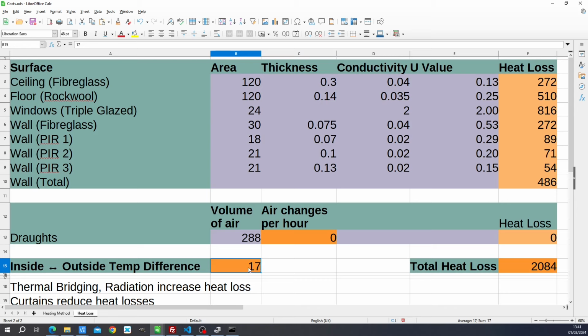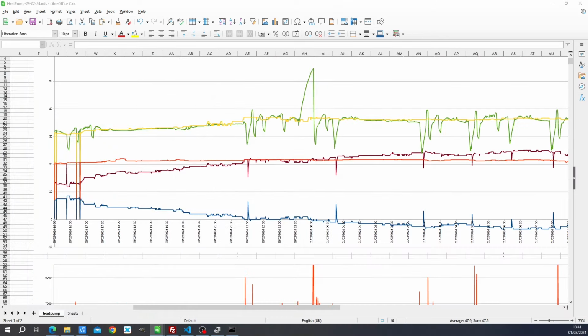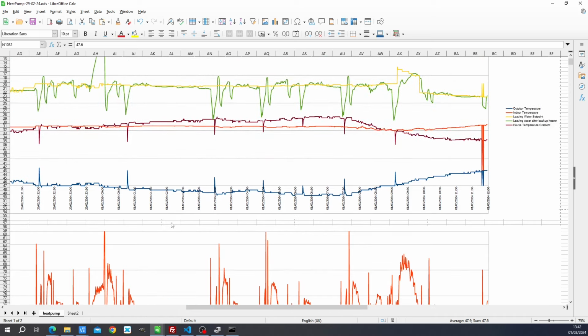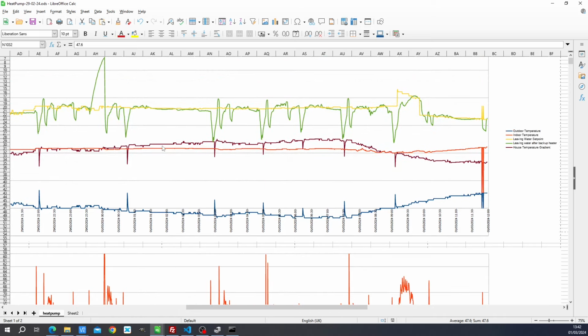That makes me really chuffed. That shows me that these calculations are worth something. It's not just a black art to calculating heat losses in a building, and this kind of information validates my calculations. If we look here, this is nice and steady. It's about 2,500 watts or thereabouts, and that is for a temperature gradient which is a bit lower, 22 degrees.